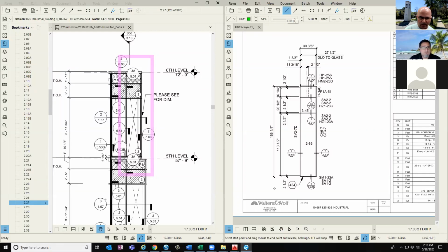At this point, what I can do is verify that the one on 603B that I saw at the sill is actually showing up correctly on the unit. The 3 on 501 that I saw in the horizontal, the same thing. Again, as I continue moving up, I'm matching to make sure that they're working the same detail bubbles from the unit assembly drawing all the way up to my unit 21606 on the head. Then I'll do the same thing going across vertically. I've got a 2 on 551 and then the 2 on 563.